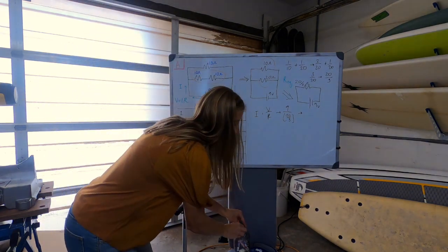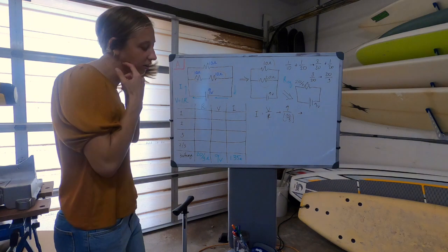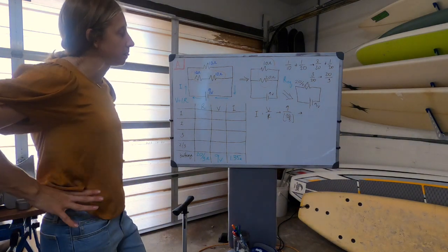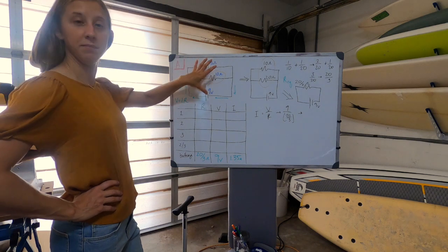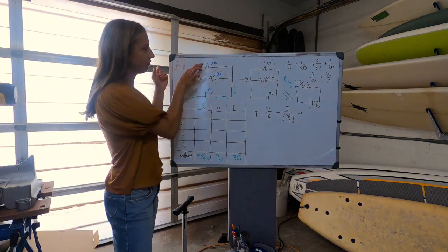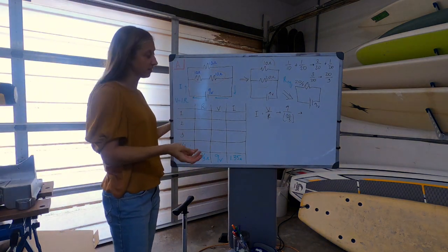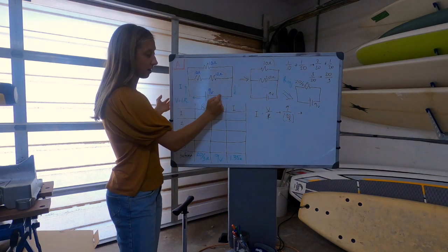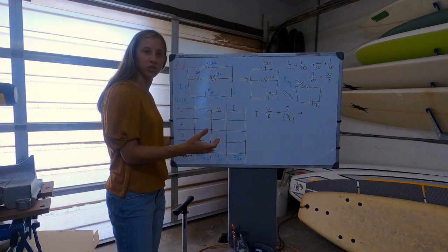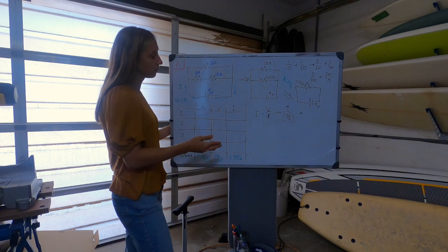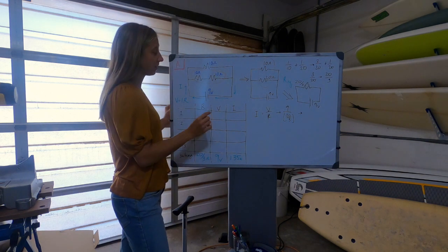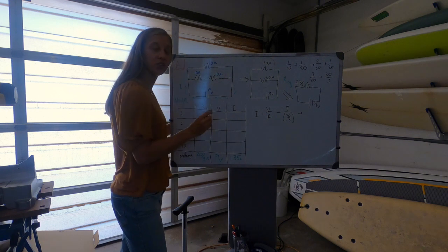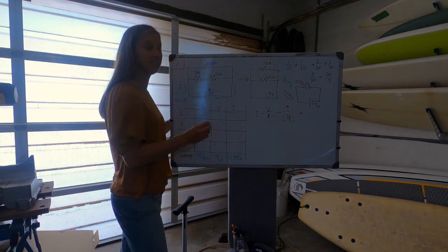What's next? Well, what else can we figure out right now? If I stop for a second and go back to my main picture, I notice that I have 2 parallel branches. And there's nothing else going on out here with the battery other than the switches, which don't really affect anything. So one thing we know from what we learned last week is that the voltage drop across branches which are parallel is always the same.